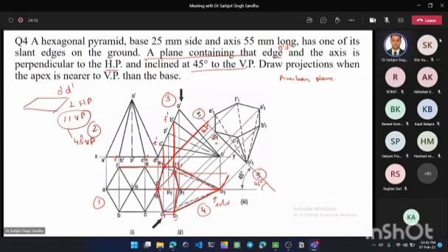So after you have drawn all these projections, now we have to transfer the distances. So mark this point D. D lies on XY, therefore D lies on X1, Y1. Measure the distance of C dash from XY. So transfer this distance, this is C, that distance has come. Measure the distance of B dash from XY. This is B dash from X1, Y1, same distance has come. Measure the distance of A dash from XY. This is A dash, the new distance from X1, Y1 has come. So in this